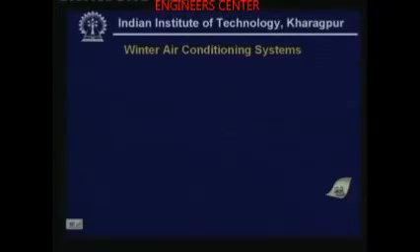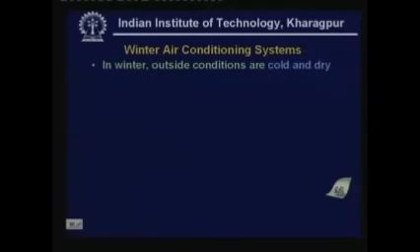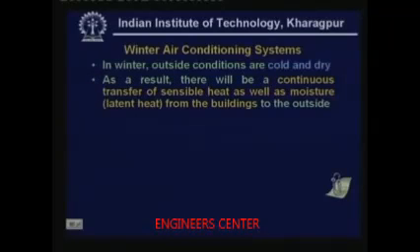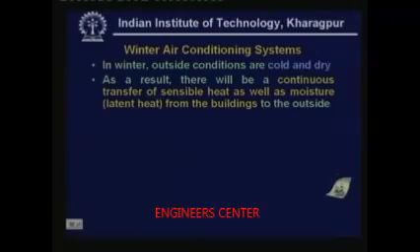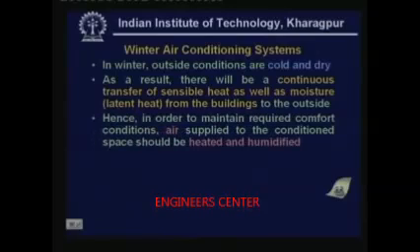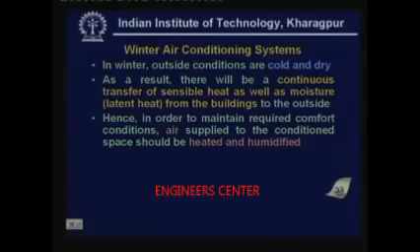Now, let us look at winter air conditioning systems. In winter, outside conditions are cold and dry. So, that means outside temperature will be very low and outside humidity will be very low. That means outside moisture content will be low. As a result, there will be continuous transfer of sensible heat as well as moisture from the buildings to the outside. That means the buildings continuously lose sensible and latent heat to the outside environment. So, in order to maintain required comfort conditions, air supply to the conditioned space should be heated and humidified.